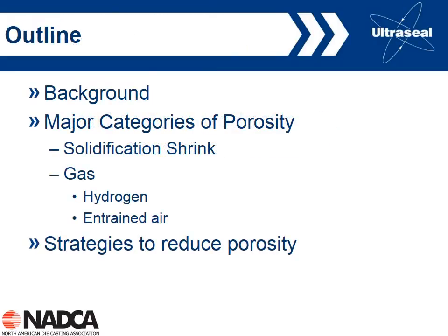So let's talk a little bit about porosity. As I say, this is going to be an introduction, part 1 of 4, and really what we're going to be talking about today is what we know about porosity in die castings and basically the causes of porosity. And the idea is to understand really where porosity comes from. Obviously, if we don't understand where porosity comes from, we can't control it. And we also want to discuss and explain why porosity tends to be a characteristic of our product, a characteristic of the die casting process.